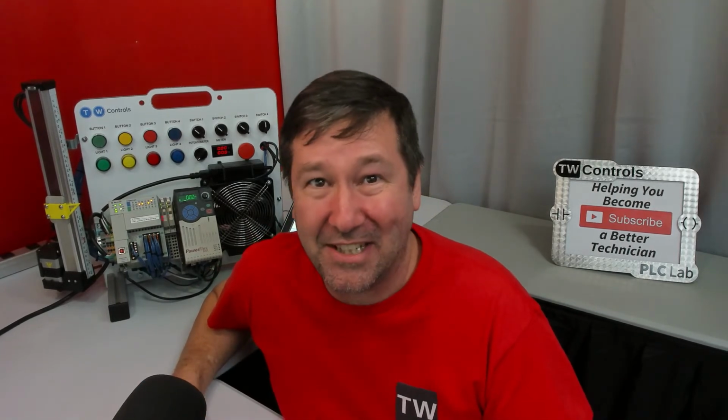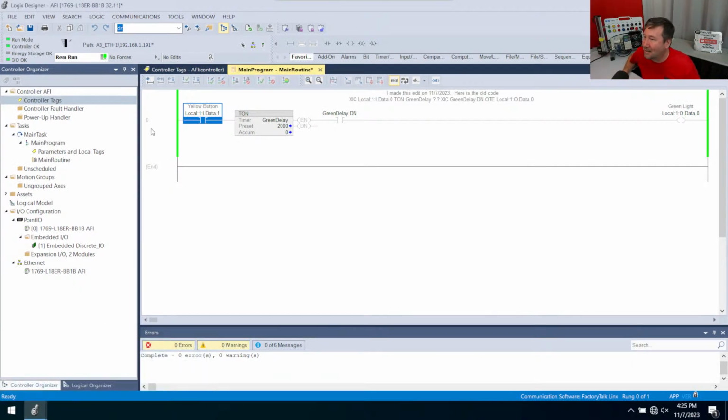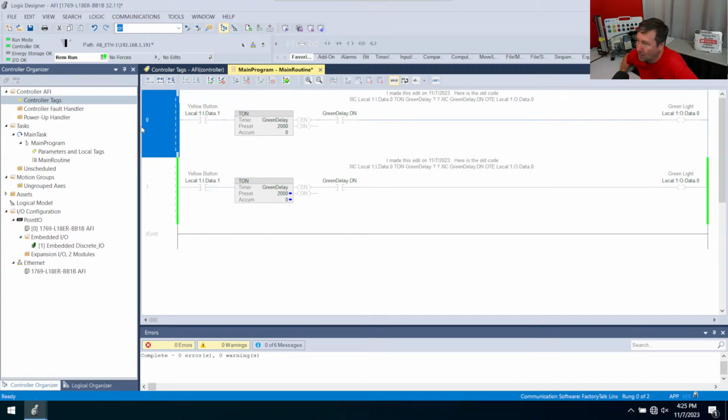And this is one thing I have to give them with their solution: I can come behind them at a later date and be like, hey, when did you start having this problem? And if they say, hey, it was on 11/7, and I look here and I'm like, huh, I wonder what that was. Well, I can start a rung edit.